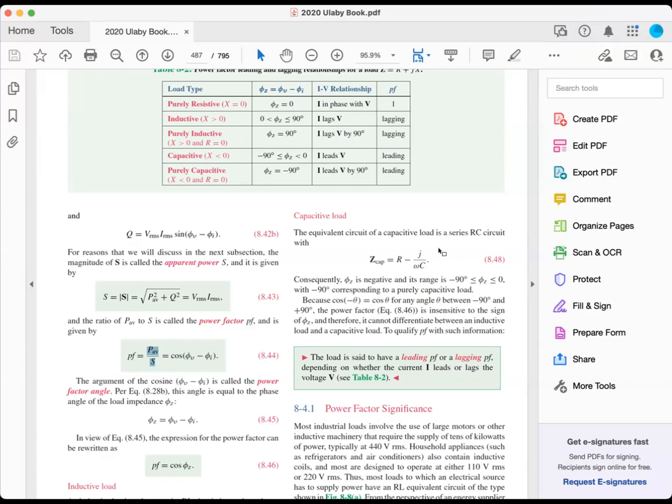Okay, so power factor is just a characteristic of a circuit that you don't really know much about. Yeah, 0.8 doesn't mean anything except that it's closer to resistive, and a 0.2 is less close to that. So it's only a comparison of itself. It doesn't really tell you anything specific, but how far or close you are to a resistive only network or system.